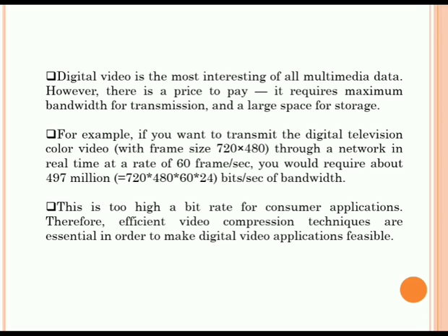For example, if you want to transmit digital television color video with frame size 720 by 480 through a network in real time at a rate of 60 frames per second, you would require about 497 million bits per second, that is 720 by 480 by 60 by 24, of bandwidth.